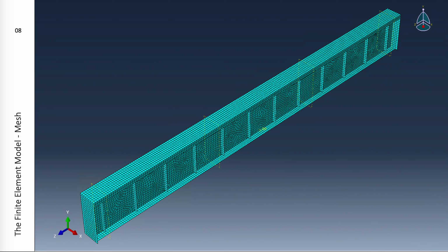The choice of mesh is governed by computational power, where a 0.8mm quadrilateral mesh of linear shell elements allowed for quick and accurate analysis. The irregularity in the web looks concerning, but results are accurate. By halving the mesh size, only a 1% difference was observed in the lowest eigenvalue in LBA.